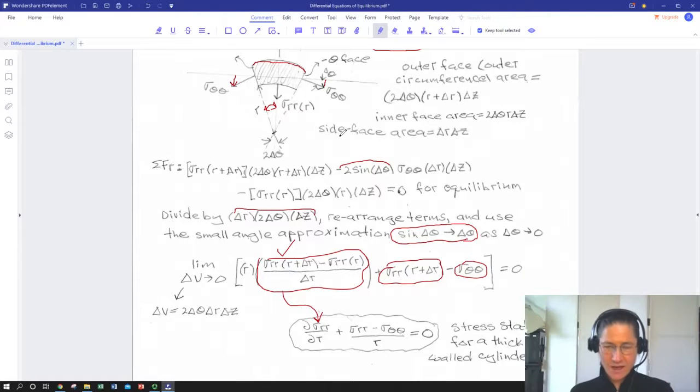We now have a way of expressing the rate of change of a stress, normal or shear, as we move in a direction orthogonally in our coordinate system through our part. So we can look beyond just what the stress is at this point, to how much the stress is changing as we go in that direction.